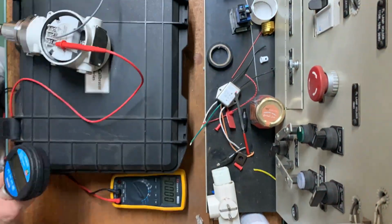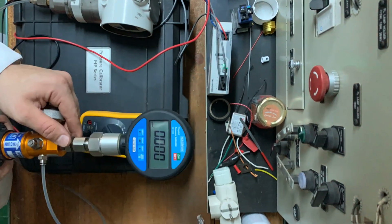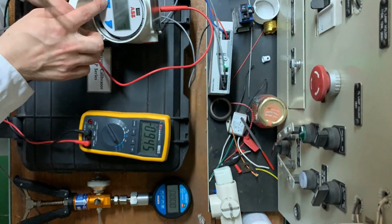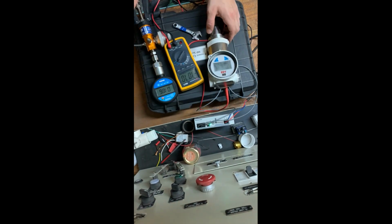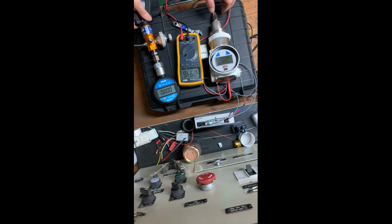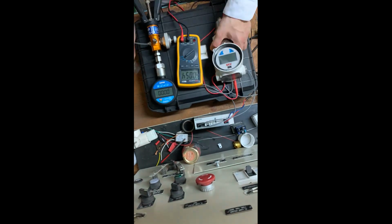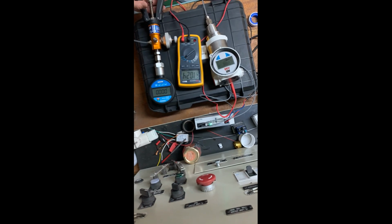But firstly I take a new sensor and try to connect it to a power supply and check its measurements. With the power supply, I connected a multimeter in the gap for checking millivolts. But I couldn't find a manual for this sensor, it has only two push buttons and no settings menu.